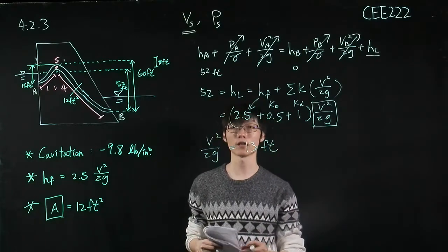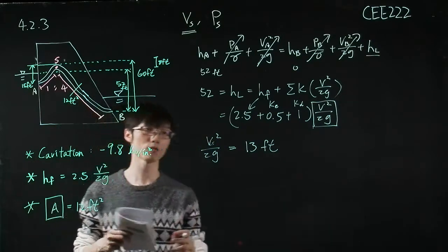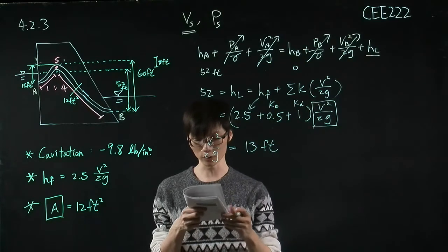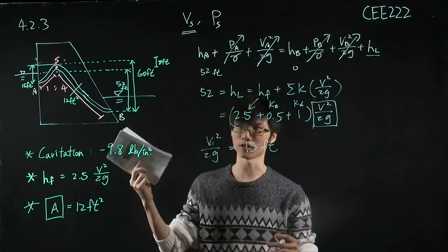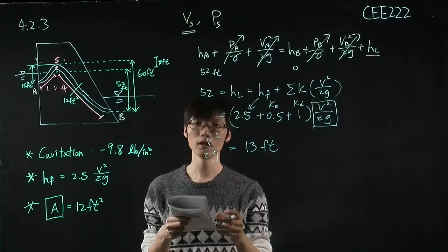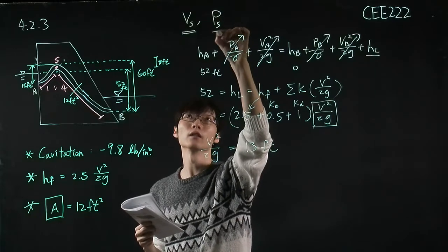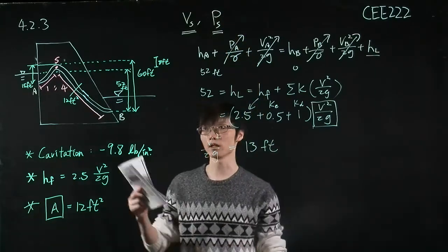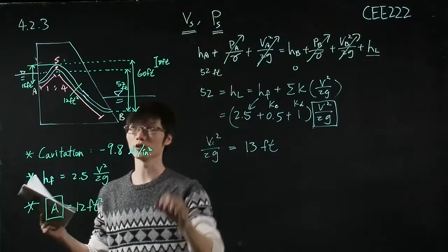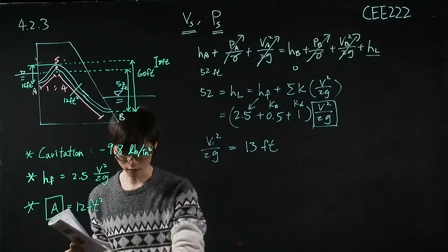Okay, that's our first step. And this V is actually V_S, because the velocity inside this spillway is equal. The area is not changing, so the velocity will remain the same. Next, we can solve for the pressure at this summit because we already know the velocity term. This pressure is the only unknown. So now, let me change to a different color.